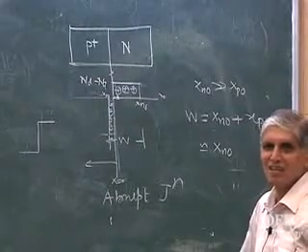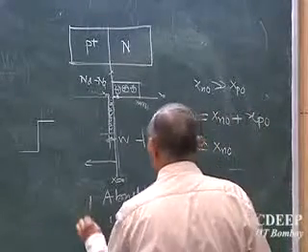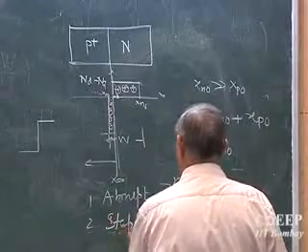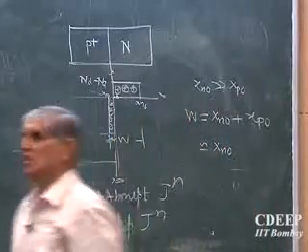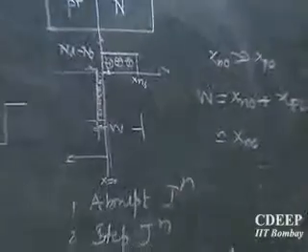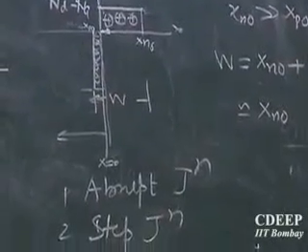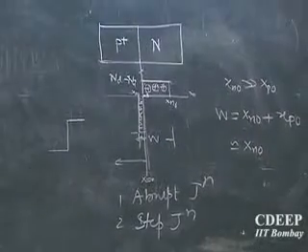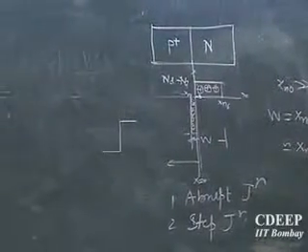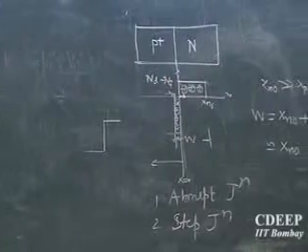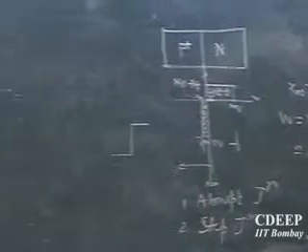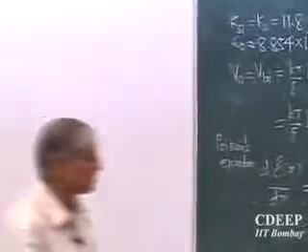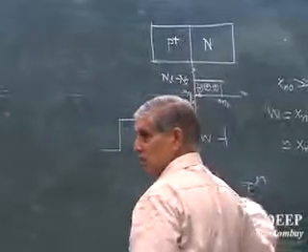What is this? It can be a step junction. So another name for this is a step junction. In the step junction, because I want to solve that equation, I thought I would first show you. On your left of x, there is a step of P, Na, and on the right there is only Nd, both are constant. However, in reality, such a junction is very difficult to make, though we try a lot, because it's the most ideal junction to work with.